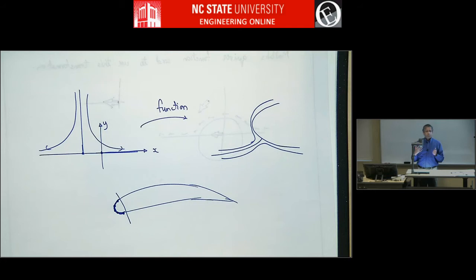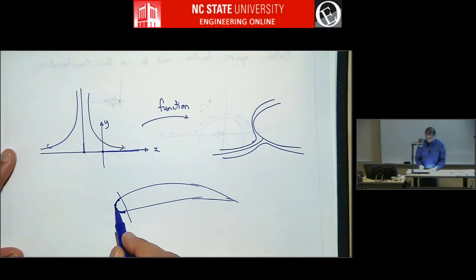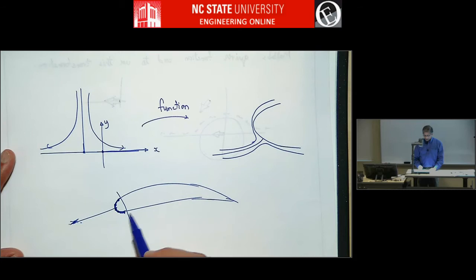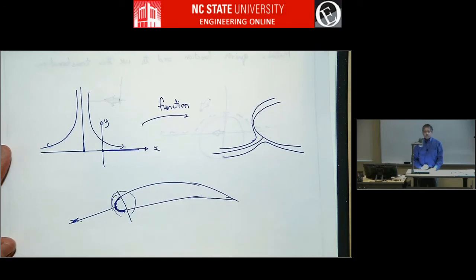One of the big problems is, how do you know what angle of attack that section is operating at? That's actually a very hard thing to measure. People have put all kinds of things. They've put probes here and they've put angle of attack measurement devices. But then that is going to get corrupted by the airfoil flow itself.